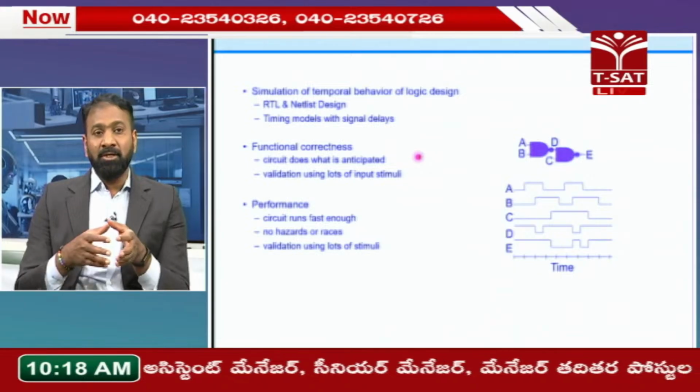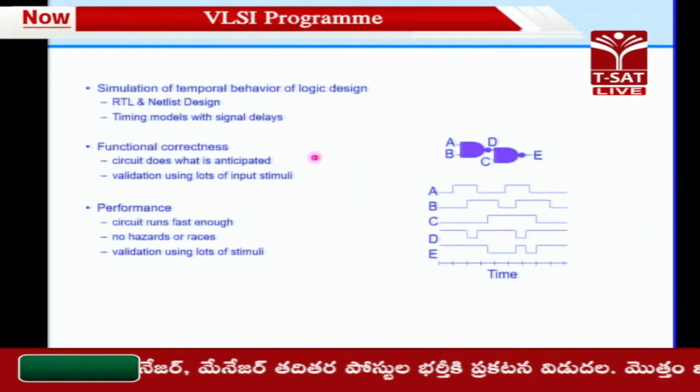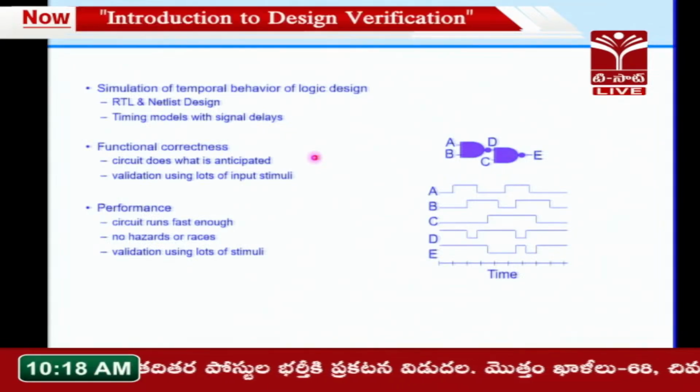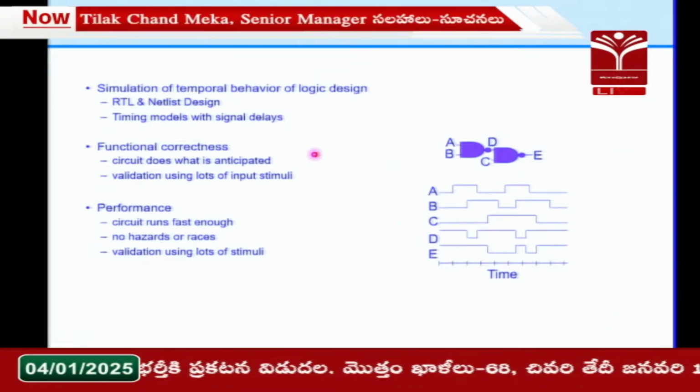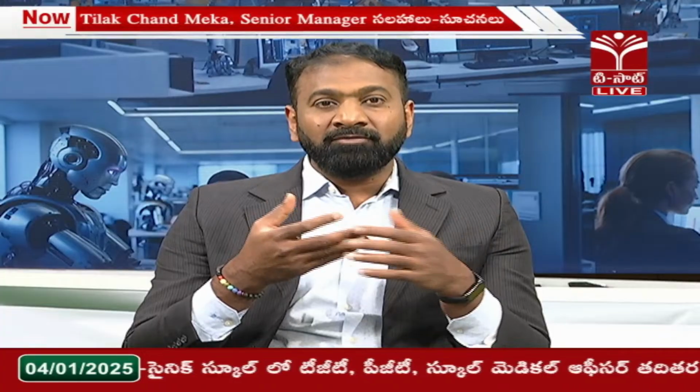And in simulation, typically if you are using Verilog, there is scope for a race. A race is where the outputs are ambiguous. Let us say I have two assignments for values, one is a equal to 0, another is a equal to 1. If I am talking about Verilog HDL, I can assign both values at the same time, but what will be the final value of a which will be considered? It is ambiguous, so that can cause a race in your design. Based on the language you are using for RTL design, there is scope for races to be introduced. So, you have to debug such races in simulation and ensure that the design works correctly as expected even in the presence of such races.